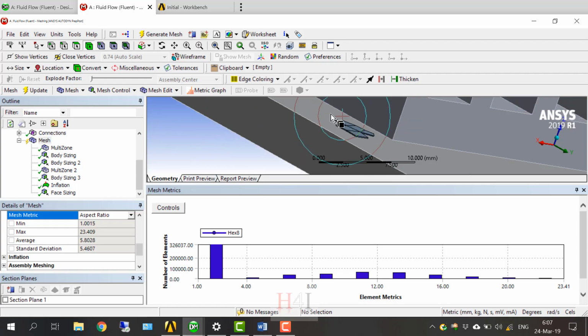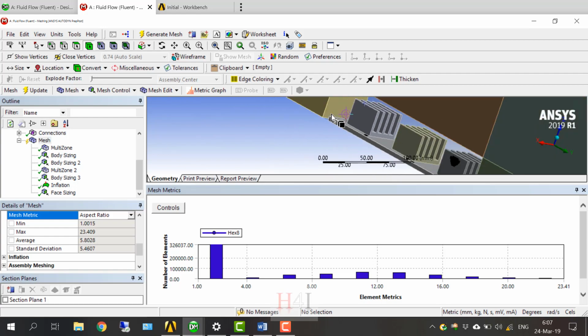And in my case, I did some modification for the film. There is a location in which I get a velocity while solving of 23 meters per second. This is impossible. This is natural convection. It will never reach this kind of value. So I know this is the location which has a problem in the mesh. So I tried to fix it.